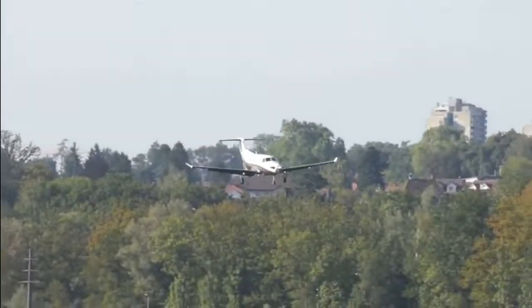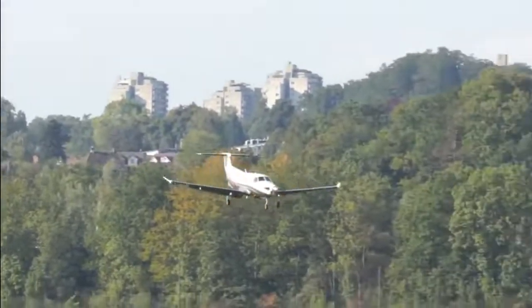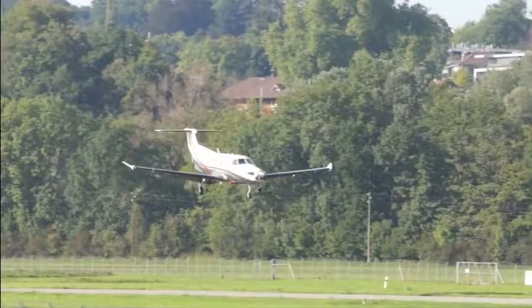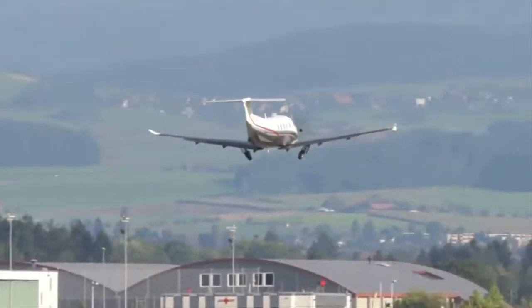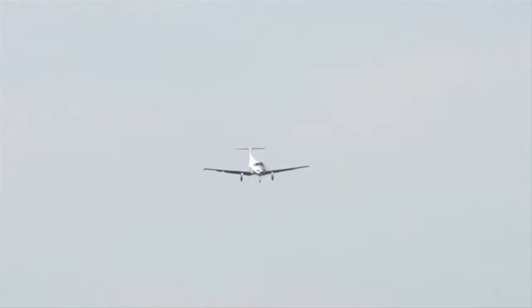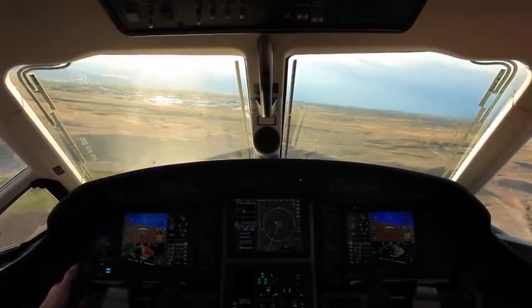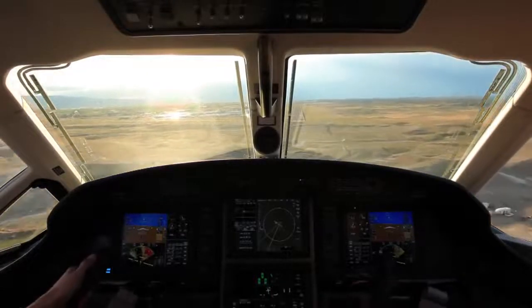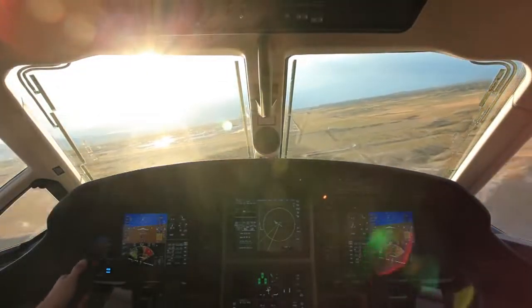As the aircraft reaches the LPV minimum altitude, the pilot must either continue to land or initiate a missed approach. As the aircraft descends past the LPV minimum altitude, the flight guidance will continue to fly the aircraft to the runway. However, minimum use height of the autopilot still applies, and the pilot must disconnect the autopilot at the appropriate altitude.